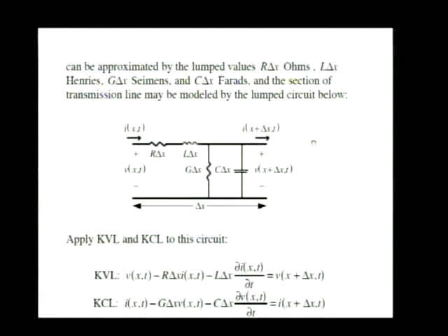Think about a 2-wire line, and I'm drawing the top wire and the bottom wire here. But this circuit works just as well for any other type of transmission line. It's just easiest to draw in the case of a two-wire line. What I'm doing here is saying that the resistance that is in actuality spread across the entire length delta x of that line, I'm lumping it all together in one location, right there, and putting a resistor in my circuit. What resistance value should I use?